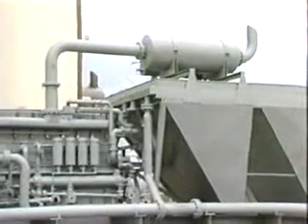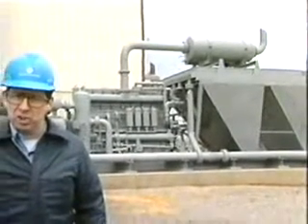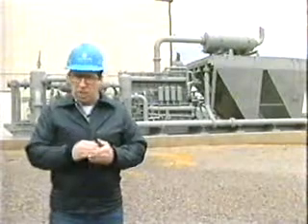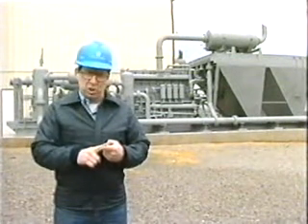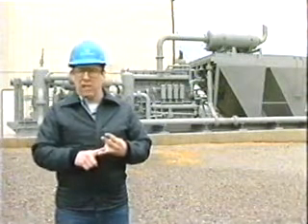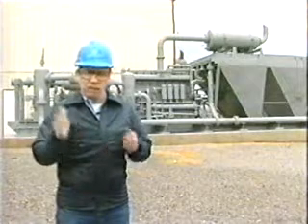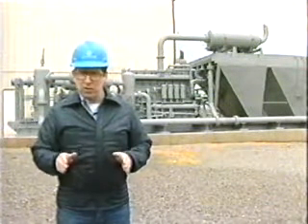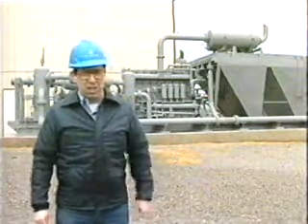The actual startup procedures depend on the type of prime mover and whether each stage has separate suction and discharge valves. Now, for our demonstration, we'll be starting up and shutting down a compressor package which has a 4-cycle internal combustion engine, multi-stage compression, a single suction line valve, a single discharge line valve, and a check valve in the discharge line. Now, your local compressor package may be different, so be sure to go over procedures for your facility before taking any action.